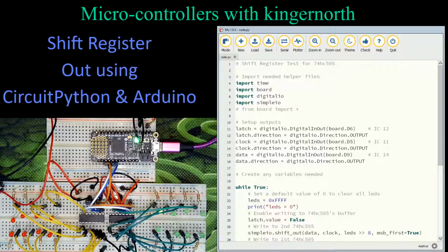So what I have here is my first set of data going here. Up in the top right-hand corner of the red ones is position Q0. Then when I move to the left, it becomes Q1, Q2, Q3. Then I move to the row at the bottom, starting on the right, and that is actually 4, 5, 6, and 7. Then if you look at the green LEDs on the right-hand side, they follow the same pattern. So the top right LED in there is Q0. So that'll be the first one that lights up when you look at that pattern.